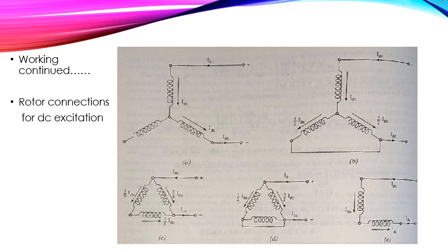So those two-phase arrangements shown in figures E and D give uniform heating but develop rather large harmonics and noise. Reduction in exciting current can be achieved by use of a multi-turn secondary, but consequently the induced secondary EMF at standstill is high, causing insulation problems.